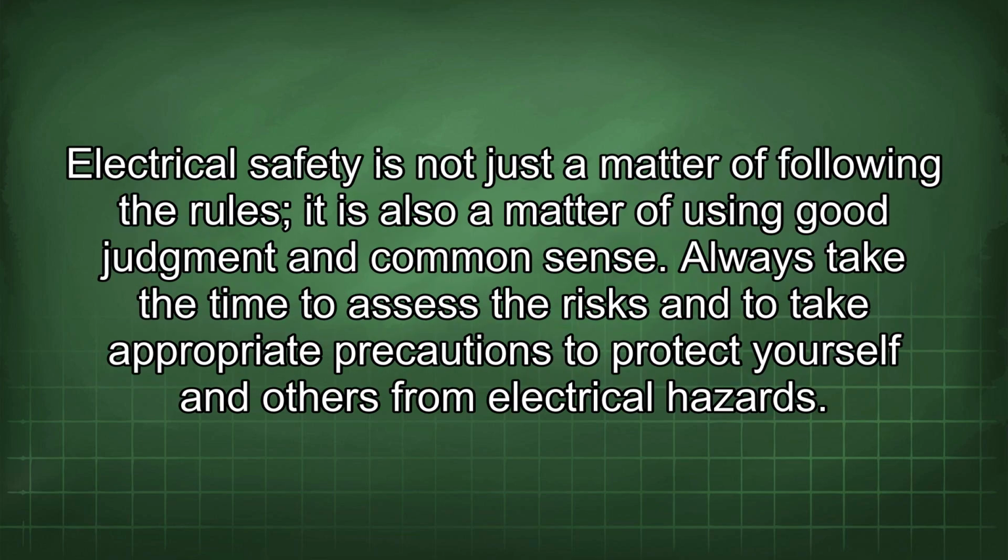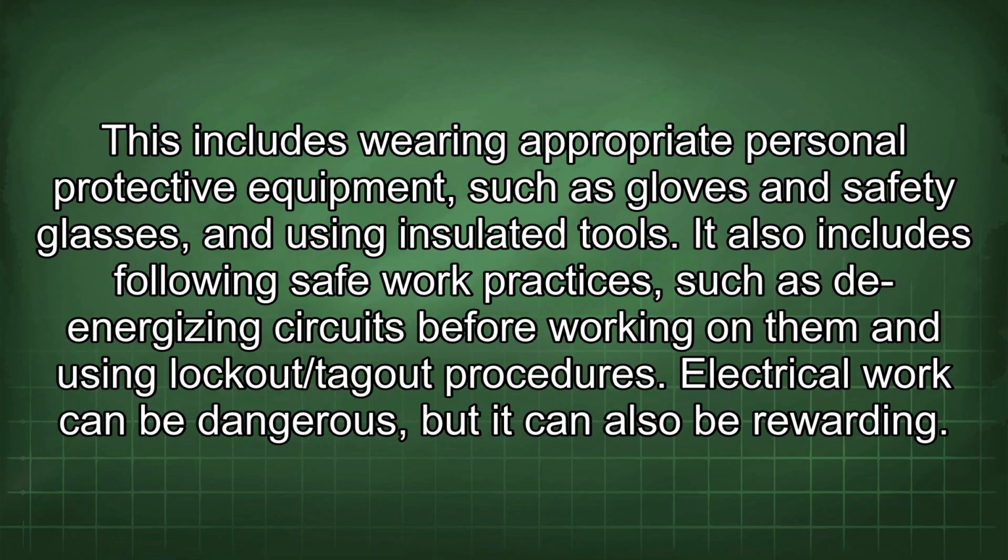Electrical safety is not just a matter of following the rules, it is also a matter of using good judgment and common sense. Always take the time to assess the risks and to take appropriate precautions to protect yourself and others from electrical hazards. This includes wearing appropriate personal protective equipment, such as gloves and safety glasses, and using insulated tools. It also includes following safe work practices, such as de-energizing circuits before working on them and using lockout/tagout procedures.